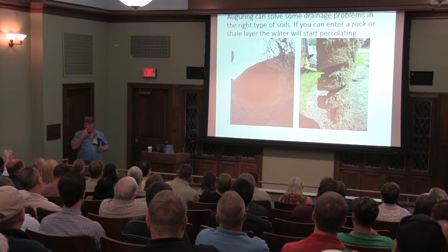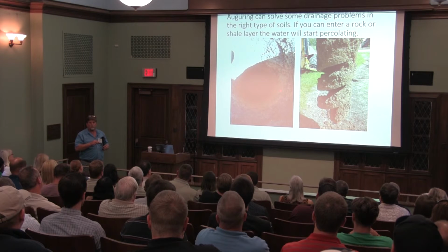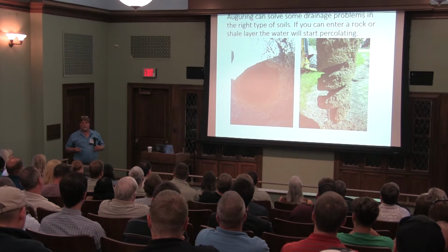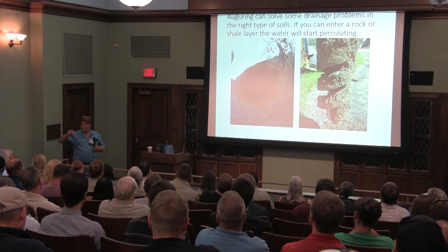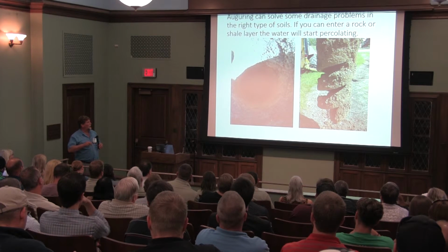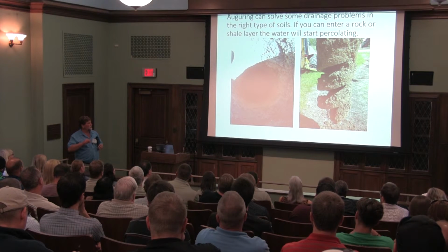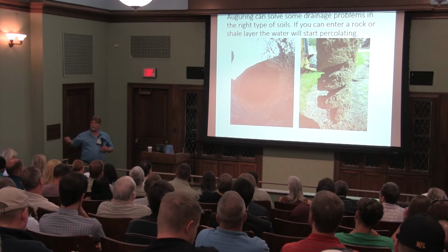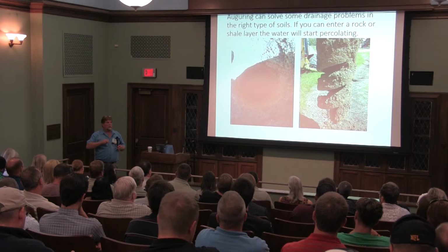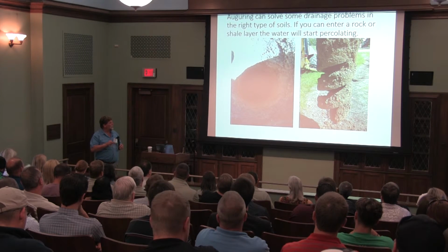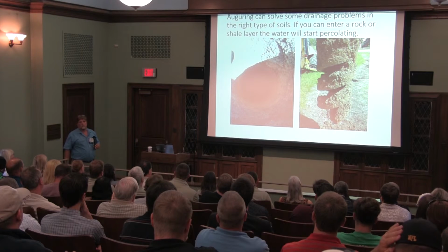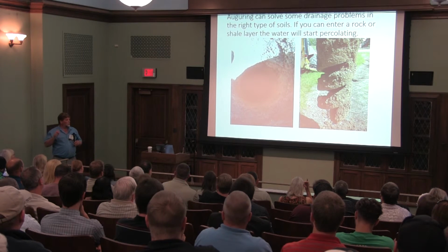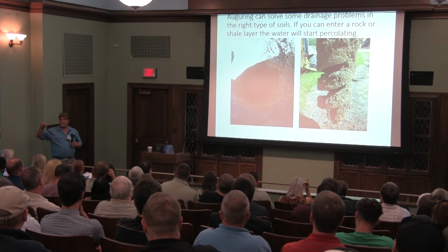We augered these trenches. And then filled this with sand. I've also filled them with gravel. And what's happening is I'm going 8 feet in the ground here. I'm hoping I'm going to interrupt a stone layer or shale layer or something that's going to take this water away. And we were able to fix all the slow ones that we had with this technique. What was interesting is what came out of the very bottom, 8 feet deep. It was solid clay. The design team, from what I understand, did one test pit.